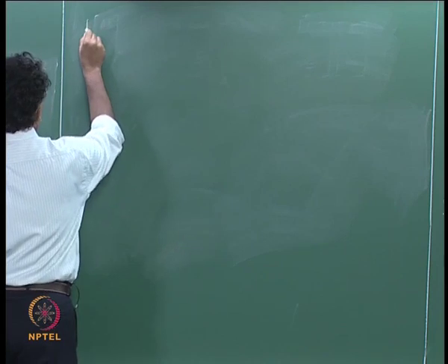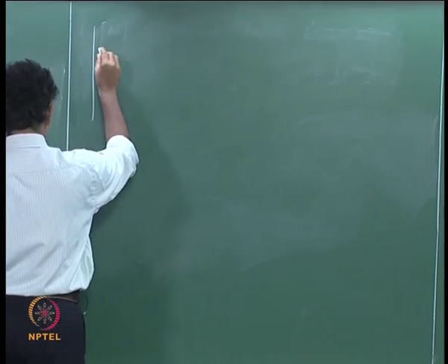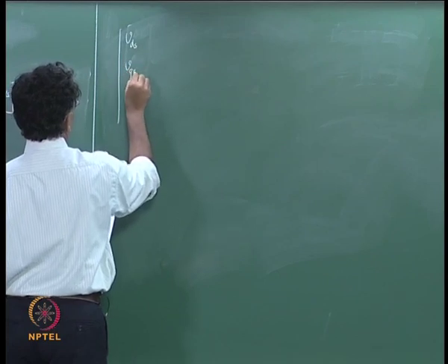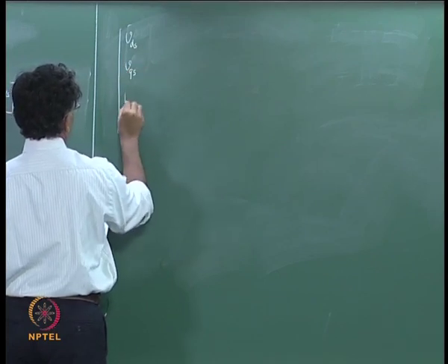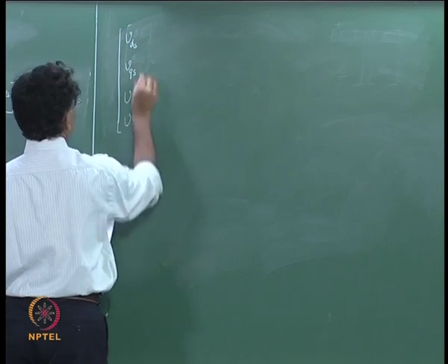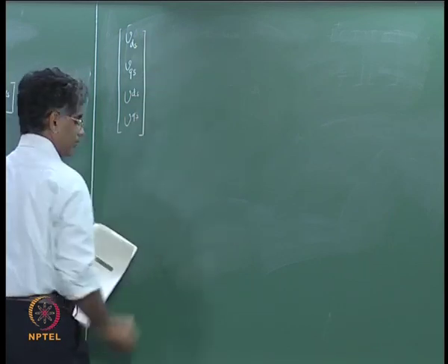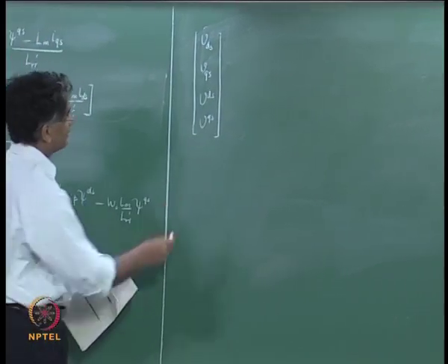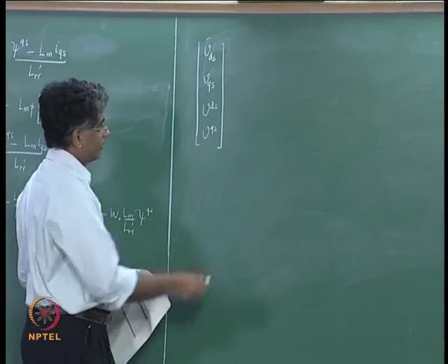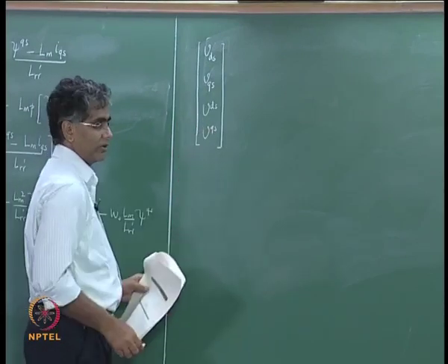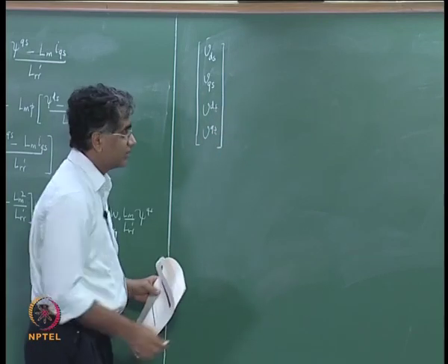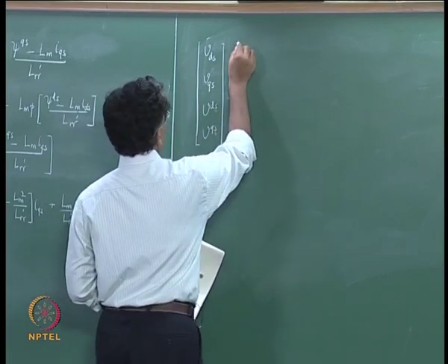What you have is Vds, Vqs, Vds, Vqs. Zero sequence component has been neglected. These are the voltages applied to the stator DQ coils, these are voltages applied to the rotor DQ coils. The term S refers to synchronous reference frame.